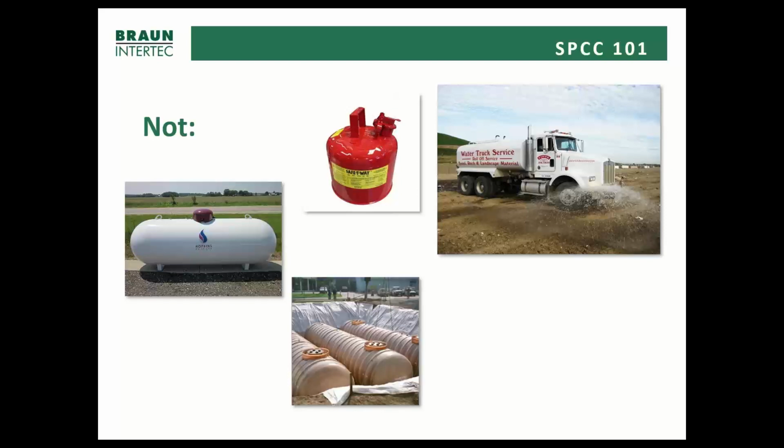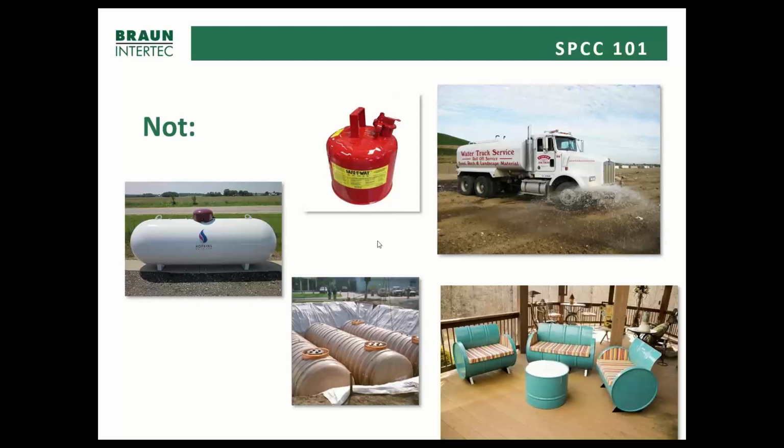Underground storage tanks: unless your underground storage tank volume is 42,000 gallons or more, the SPCC rule does not apply. The SPCC rule, again, focuses on things that are aboveground and the piping that connects them. Underground storage tanks are already adequately regulated by your states and other programs.